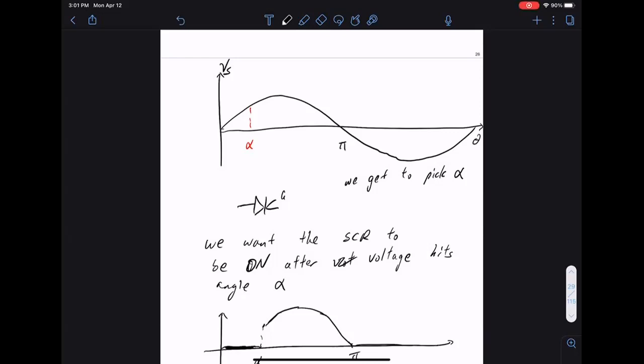Quick question. So you said we just vary the location of the alpha, right? Yeah. So basically, if usually the voltage maximum is 120, and you want 50, you just vary the alpha until the max is 50, right? So it's not that, because this is a sinusoid, so it's not that you want half the voltage, half the alpha. It's not a linear relationship, but we'll get to that relationship. But the idea is correct. Alpha is our control parameter.